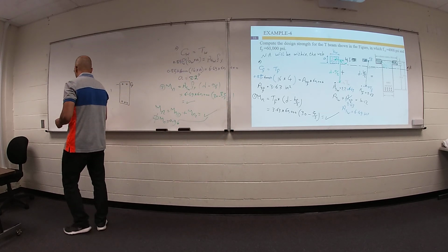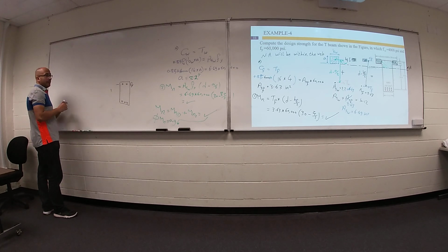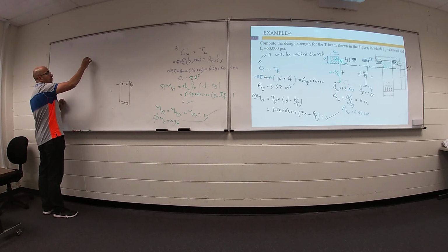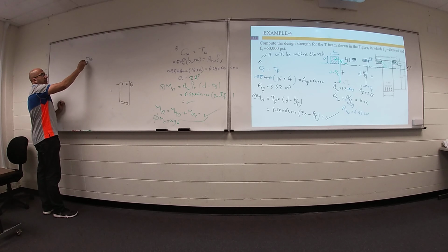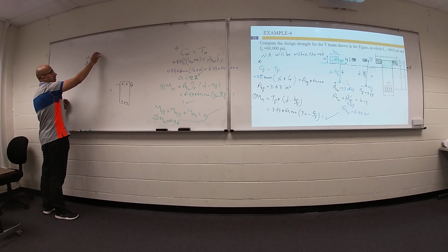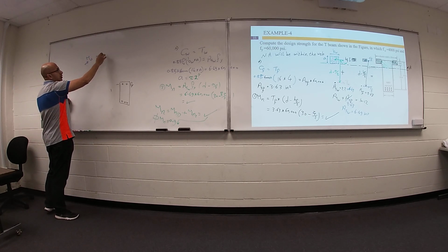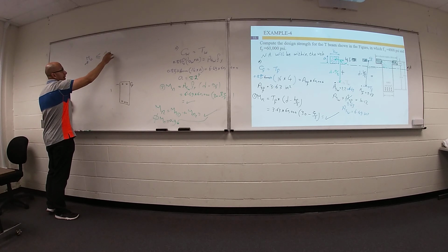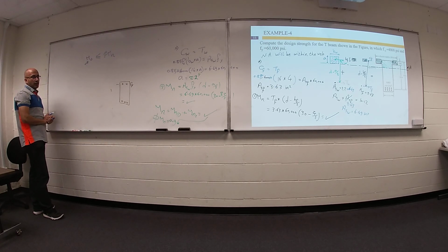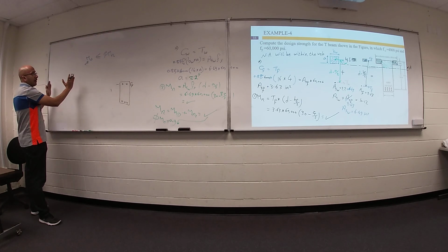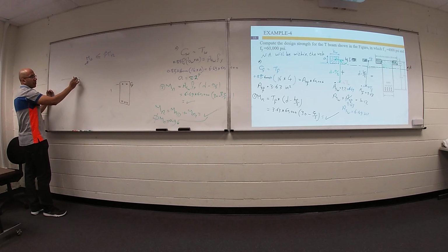Remember, at the end, your moment from structure analysis results must be smaller than or equal to your design moment for your beam. So we have two parts. First part, we need to do structure analysis.